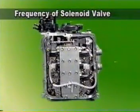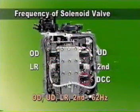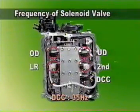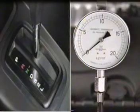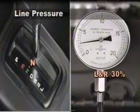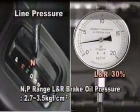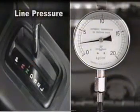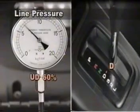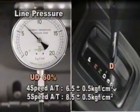Frequency of solenoid valve is approximately 62 Hz and is controlled by TCM. However, the frequency of the damper clutch control solenoid valve is adjusted to be 35 Hz. The line pressure of Hivec automatic transaxle is applied only 30% of first speed and second speed oil pressure in park and neutral range. And in high speed range of third or fourth speed, only 60% of first and second speed oil pressure is applied.